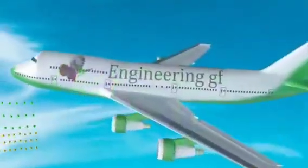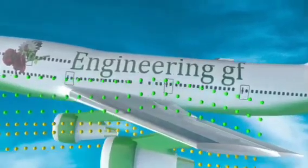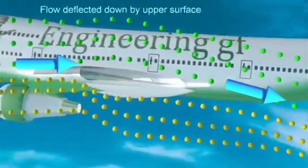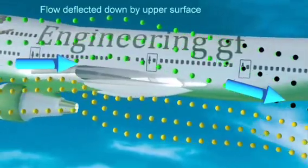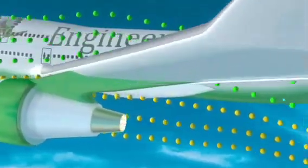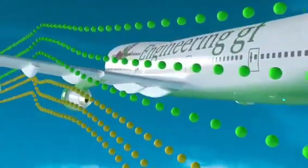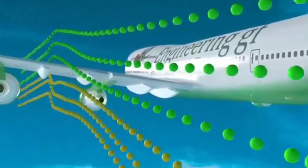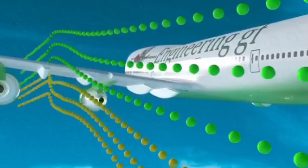The downturning of the flow is not produced solely by the lower surface of the airfoil, and the airflow above the airfoil accounts for much of the downward turning action. Since both surfaces are involved in deflecting the flow downward, more air is deflected down and thus more lift is generated. Though correct, this theory does not provide any detail about how the turning of flow is taking place over the wing. It simply says that because the flow is turning down, the airplane must be pushed up.